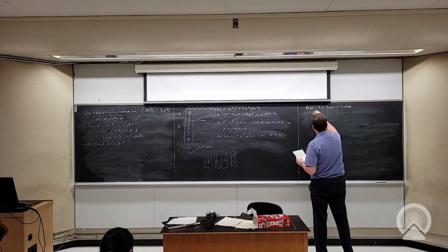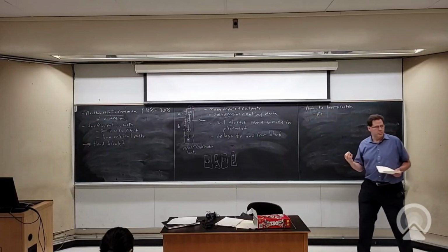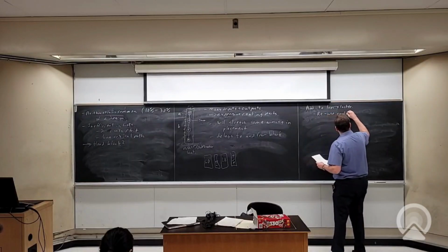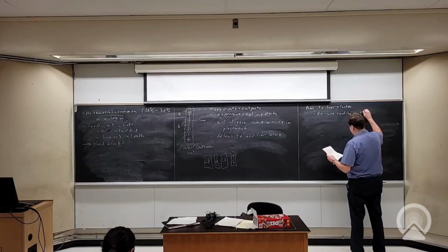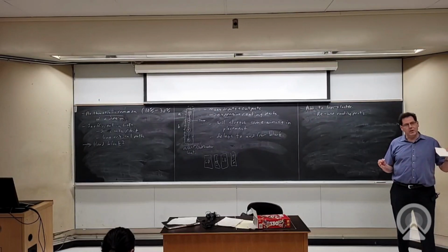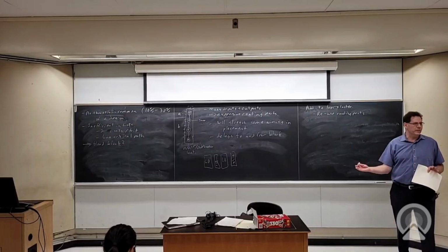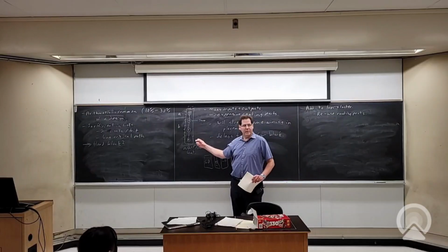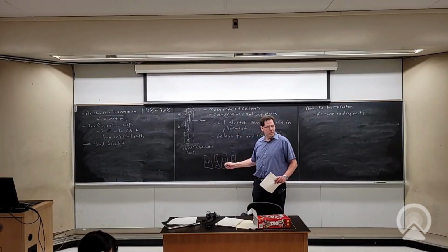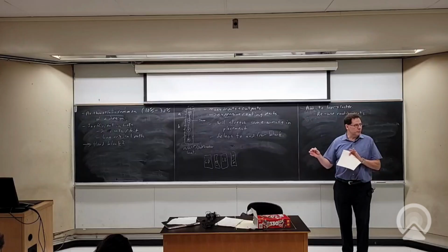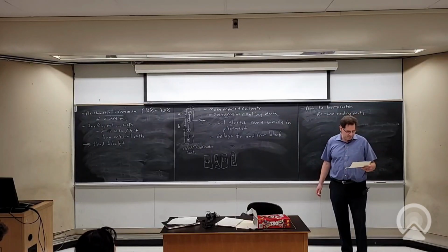Okay, so why is this good? Because the logic cluster already has all these routing ports. We'll reuse them. Okay, so one way we could do that is we could basically say we've got a logic block and you can either use the LUTs or you can use this adder structure. And now we'll basically share the same routing ports. So that would actually be better than what we did here. So we'd have a mixed block that could be either a logic block or an adder. And we don't have to add any more routing ports. We'll just reuse them. It kind of has 2 modes of operation.